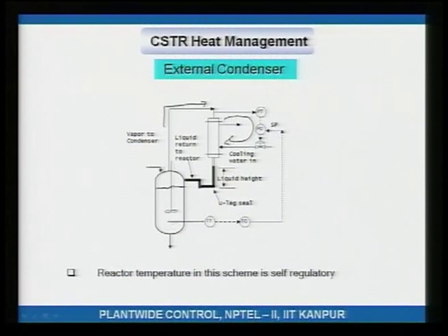Okay. So, if you want a certain temperature and the temperature is increasing, what you would do is reduce the pressure set point and then temperature will get back down. Notice that in this scheme you are not controlling both the temperature and the pressure, you are controlling the temperature by adjusting the pressure set point.